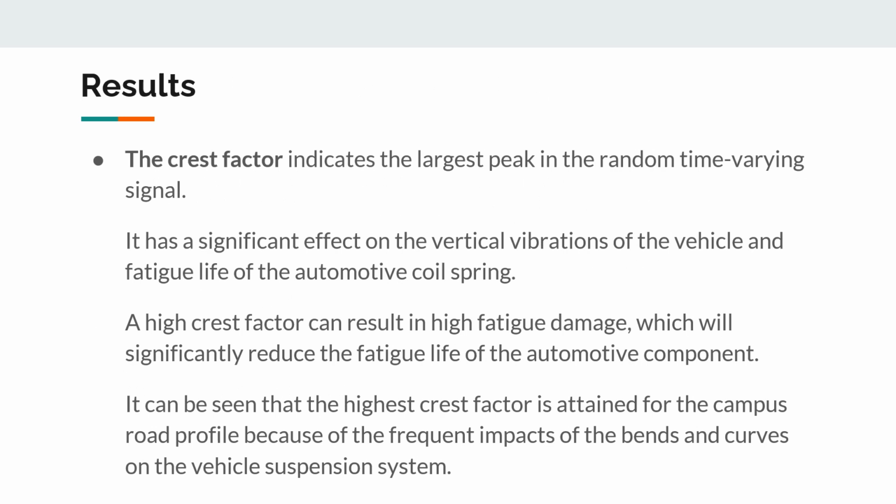The crest factor indicates the largest peak in the random time varying signal. The crest factor has a significant effect on the vertical vibrations of the vehicle and also the fatigue life of the automotive coil spring. A high crest factor can result in high fatigue damage, which reduces the fatigue life of the automotive component. It's observed that the highest crest factor is attained for the campus road profile because of the frequent impacts of the bends and curves on the vehicle suspension system.